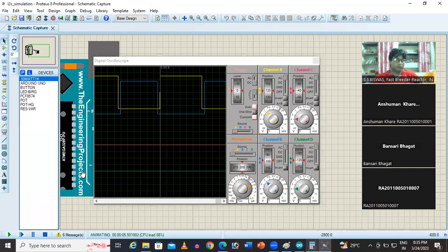So this concept is called generation of dead time, which is very, very important in power electronics applications. Say you are going to make a 4-quadrant DC to DC chopper. That time you need the complementary pulses. And when we'll be dealing with complementary pulses, you should be very careful that at any instant, both the switches should not be on together. So this is the very fundamental concept to generate dead time for the complementary pulse. So hope you have understood this code.